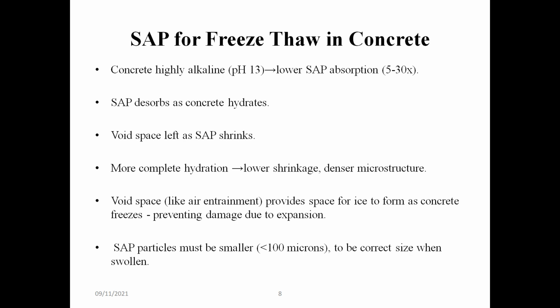SAP desorbs as concrete hydrates. Void space is left as SAP shrinks. This gives more complete hydration, lower shrinkage, and a denser microstructure. Void space, like air entrainment, provides space for ice to form as concrete freezes, preventing damage due to the expansion. SAP must be smaller than 100 microns to be the correct size when swollen.